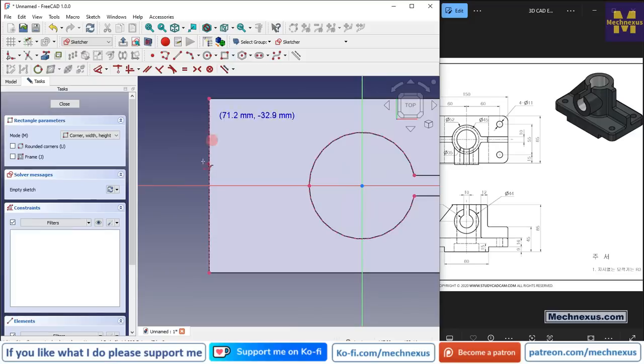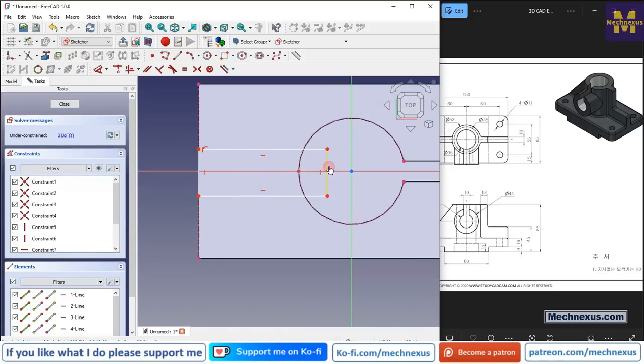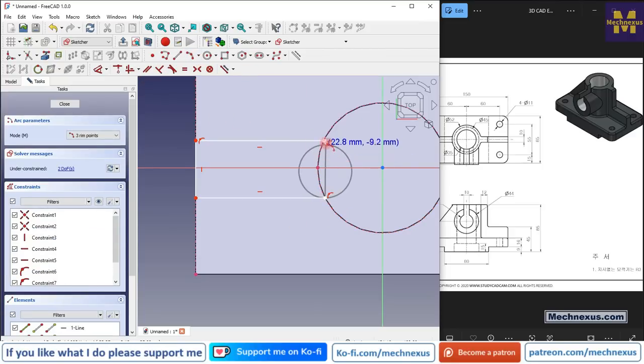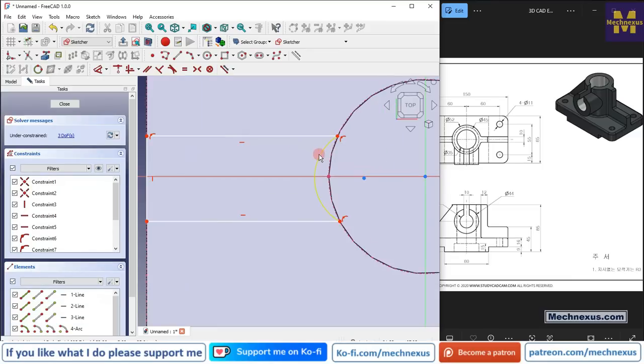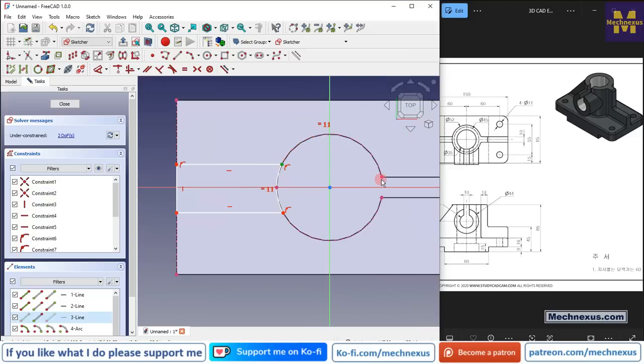Now click on the rectangle and create a rectangle, and now let's select this line and delete it. And now in the same way we will trim this extra geometry. And now I will select a 3-point arc and create one arc, and I will select this arc and this arc and make it equal. Now we will make it symmetric. We can also make this horizontal. If not symmetric, we can add the relation with this edge.